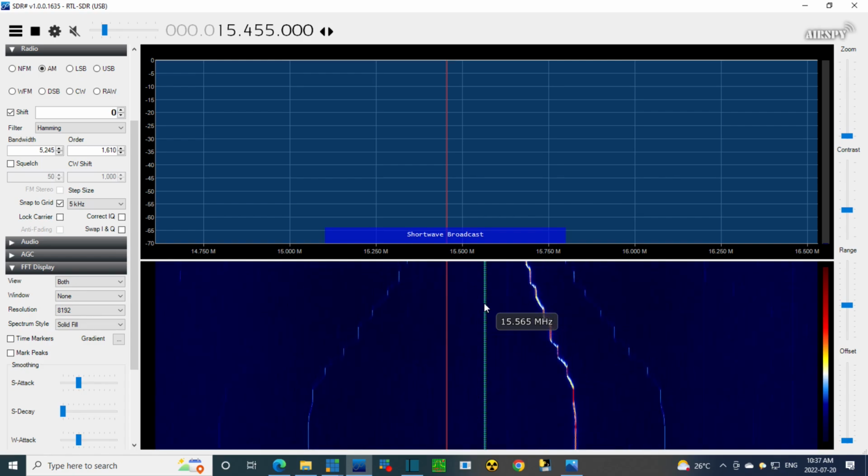More clicking and popping. Earlier on, when I was working on the radio and it was clicking and popping, I noticed the dim bulb lights, which were on at the time, were also going up and down, and that was almost certainly that capacitor drawing extra current out of the radio power supply.